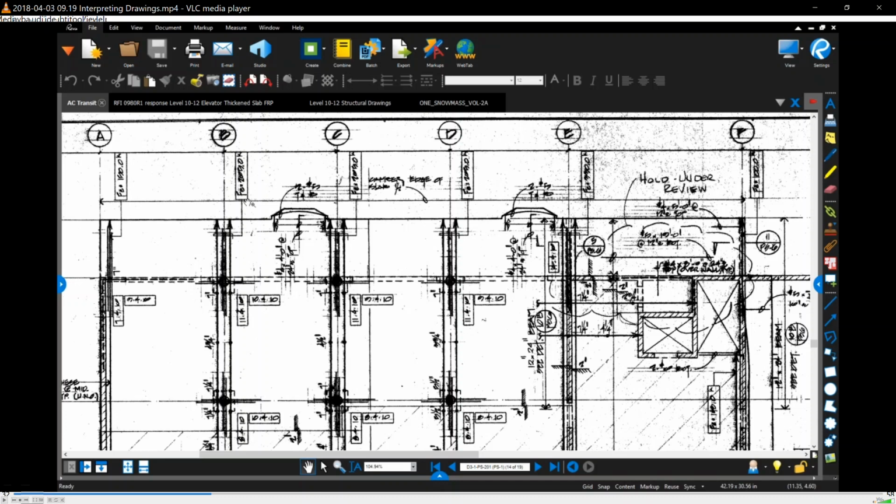All of this information, you could take from this and fill out the post-tension slab strengthening summary table. The information on here includes the tendon profile. The tendons go down at the midpoint and up at the support, and that gives you D, your depth, or DP. And there's other stuff you can get.